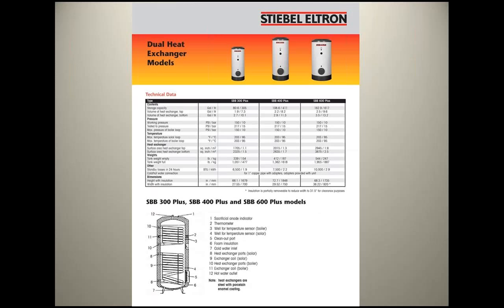And for a while in California, you couldn't use these because this is what's called a single wall. There's only one wall between this tank and the potable water. So there was concern that if people put in non-food grade glycol, ethylene glycol, which is poisonous, instead of propylene glycol, because ethylene is much cheaper and you can get it since you can put it in your car radiator, but it's poisonous, and there's a leak in this thing, it would pollute the water supply.